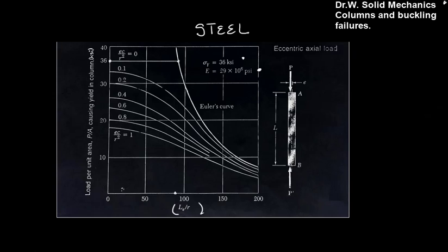And on this side, we have the stress generated, and it's plotted versus an EC on R squared term, where R is the radius of gyration. And what we can do is look up the EC on R value and trace it across to the L on R slenderness ratio. And from there we'll know the yielding stress without having to solve it through the secant formula.